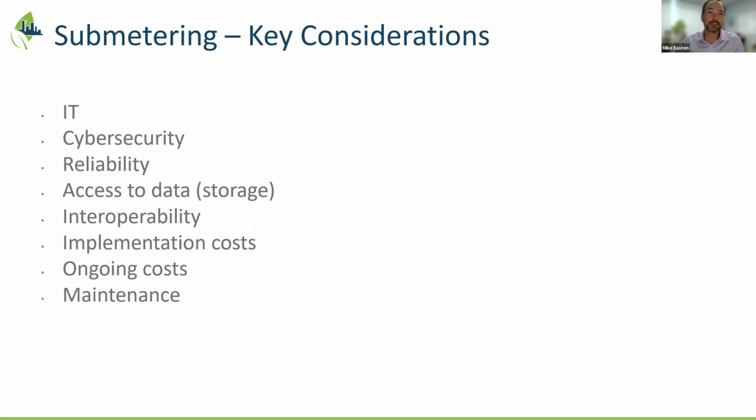Because if the meter supplier is providing one protocol and the building automation company is looking for another, it's going to be a really expensive fix to replace the meter with something the BAS can utilize. So in institutional and commercial properties, we're really seeing Modbus and BACnet being the two most utilized open protocol solutions. There are some others still in some meter manufacturers, like Hart and Profibus communications. Those are just not being utilized very much anymore. So I try to stay clear of those and really factor in Modbus or BACnet,